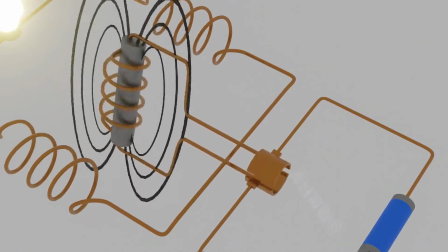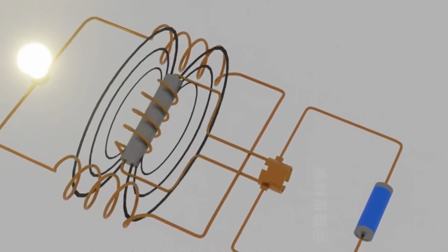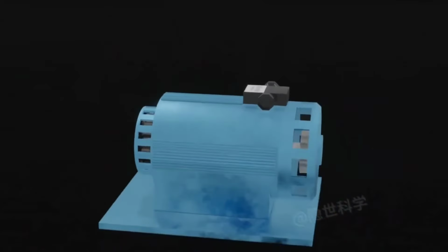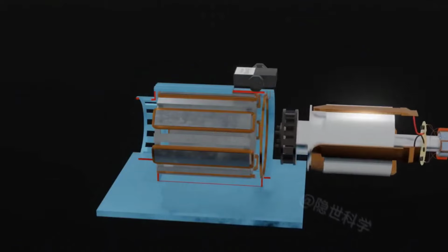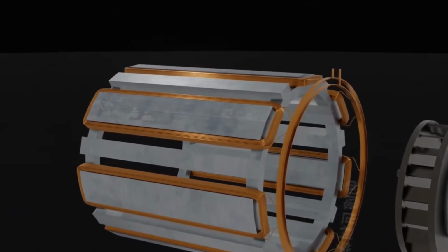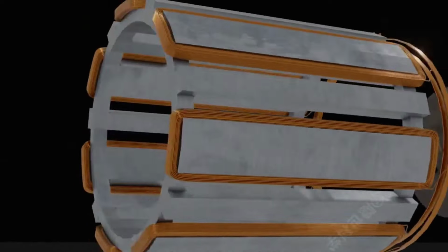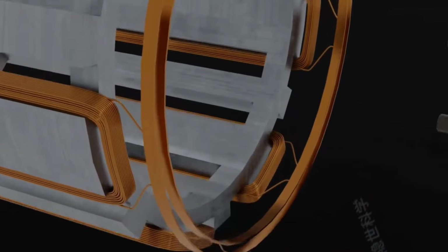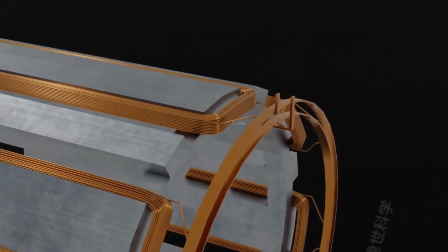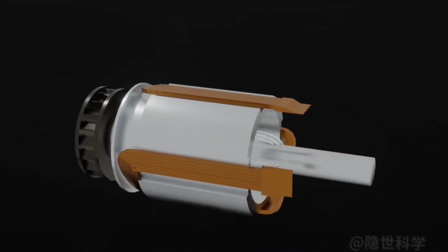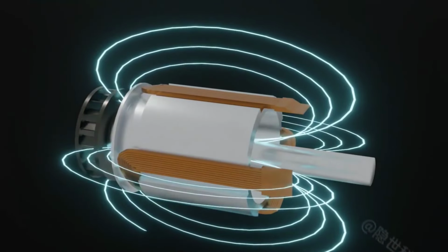So there are two kinds of coils in the generator: stator coils and rotor coils. The stator coil is where the magnetic field is cut. The stator consists of multiple coils installed on the stator winding. Then all stator coils meet two terminals as output. The function of the rotor coil is to provide a magnetic field. Since this is not a permanent magnet, direct current needs to be passed to excite the magnetic field. The stronger the magnetic field formed, the larger the current.